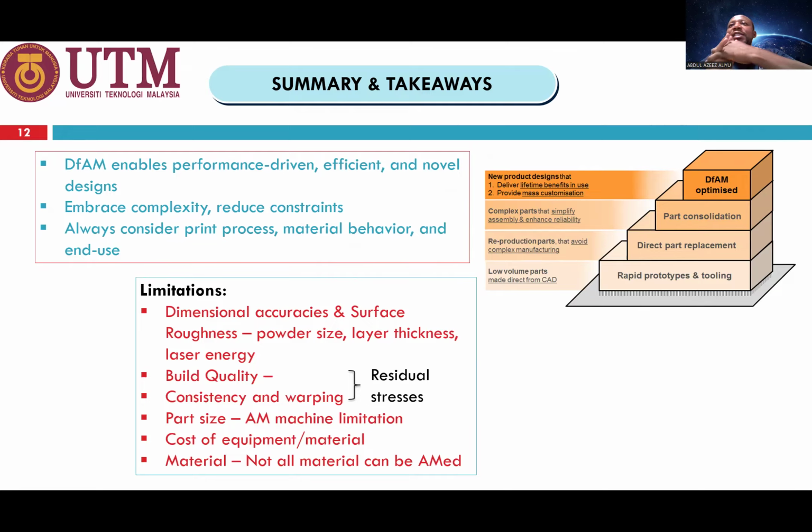Aside from the numerous advantages of this process, it also has a number of limitations, like dimensional accuracy and surface roughness. Actually, the surface finish produced using additive manufacturing is quite bad. And this depends solely on the type of powder size, the layer thickness, and the laser energy used.